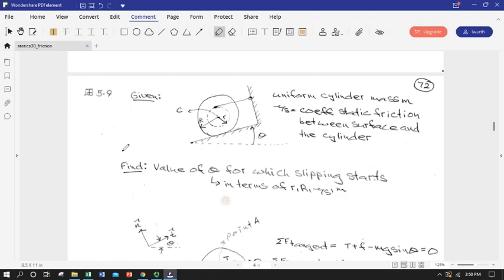So one of the challenges with friction is, in order to get the direction of the friction force correct, you have to envision what is the direction of imminent motion that we're trying to prevent, in this case, to keep things in static equilibrium. Friction vectors have to be drawn in the correct direction. They won't self-rectify like some of the force directions we've seen in earlier equilibrium analysis. So that's probably the biggest challenge.